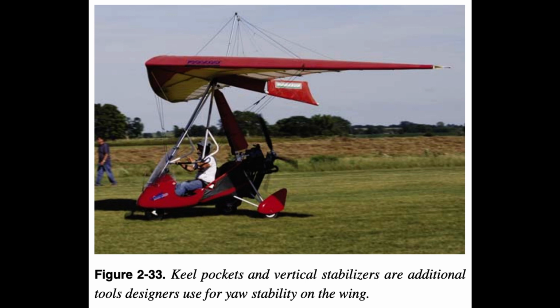Carriage moments. The wing is a significant factor in the design of yaw stability, but the carriage can be a large factor also. If the area in front of the CG is greater than the area in back of the CG, and the wing yaws to the side, then the front would have more drag and create a moment to yaw the WSC aircraft further from the straight flight.